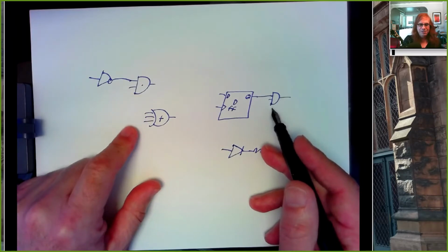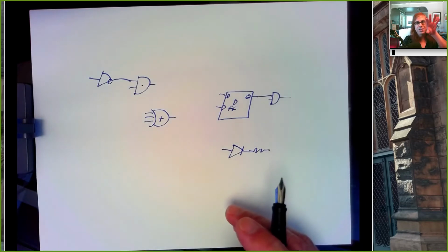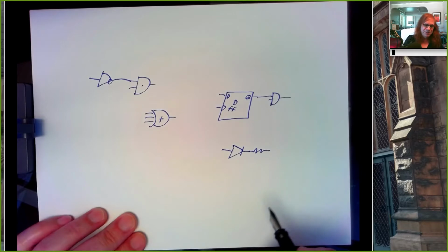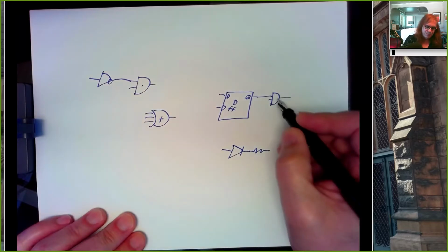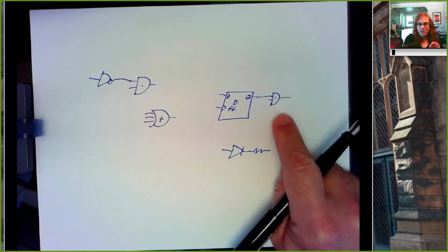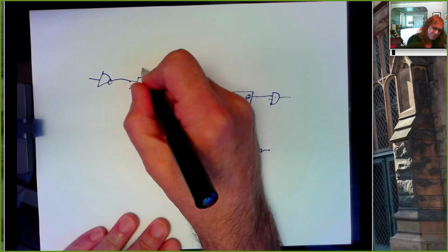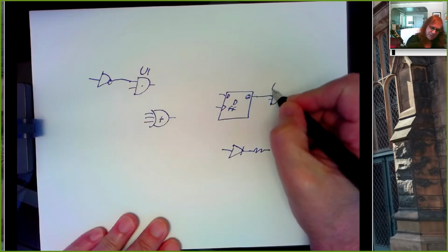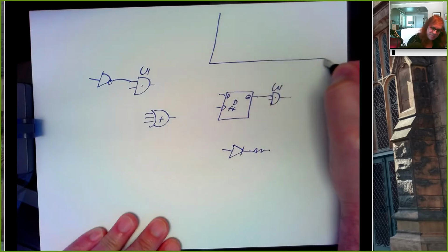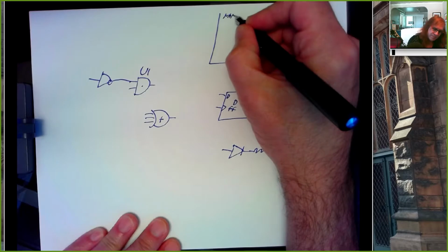But, you know, if you're going to implement this, you probably want fewer chips rather than more, so unless you're breaking it into 3 logical pieces, like you might have done with a traffic light, you might put these in the same physical chip, or you might have different chips. But you got to indicate that on the schematic. So we label these, right? I would label this U1, and I might label this U1. And then we have this component ID block. There's a name.